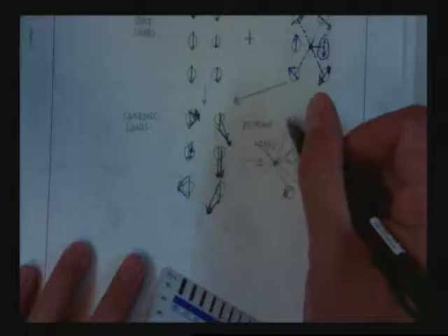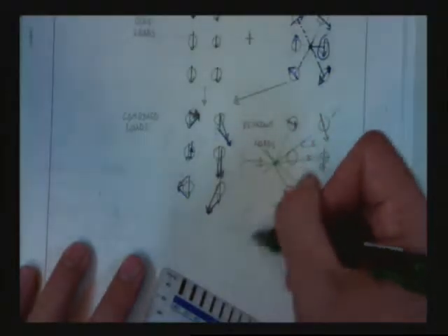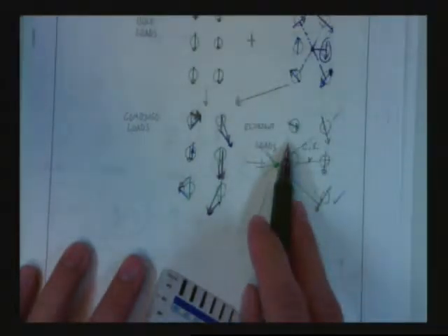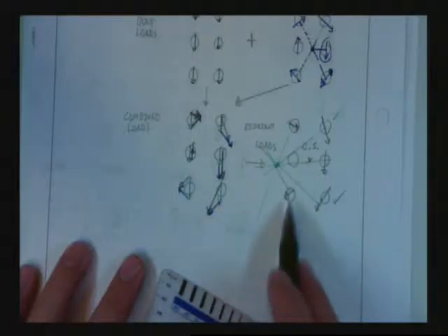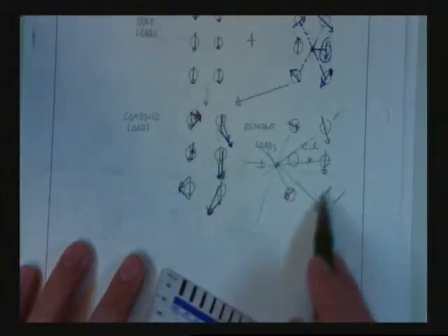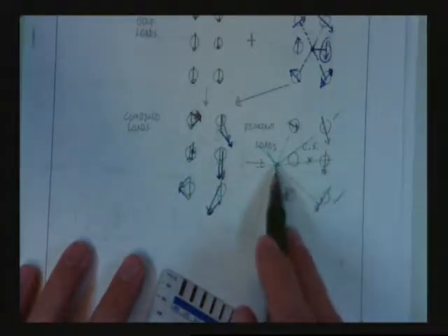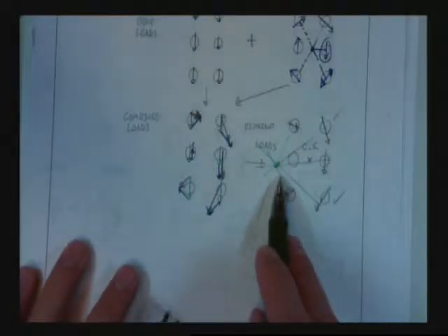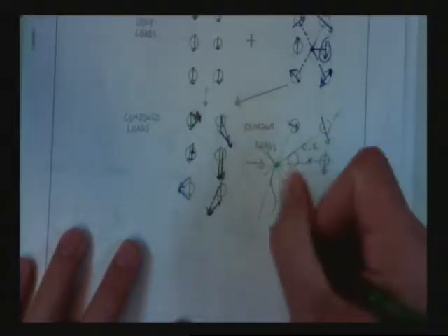Hard to see what I'm doing, huh? So I basically drew a line that's perpendicular to this. And there's a whole bunch of them, right? Same thing. Drew a line through this, a line through this, a line through this. But in only one spot do all these lines coincide. There's only one spot where all of these lines meet. And that's called the center of twist.